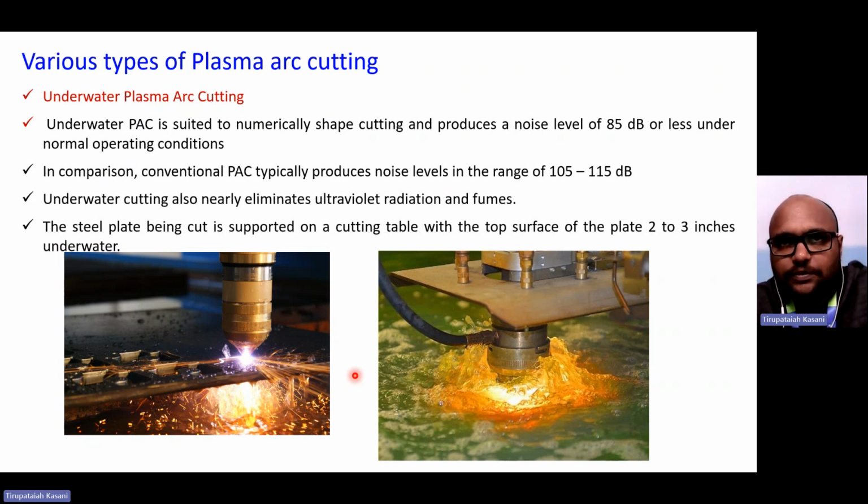There it involves mechanical energy. In electron beam machining, high velocity electrons impinging the top surface create thermal energy, melting and evaporation. But in ion beam machining, positive ions impinge on the top surface. That is, mechanical energy is responsible for removing the material from the workpiece.